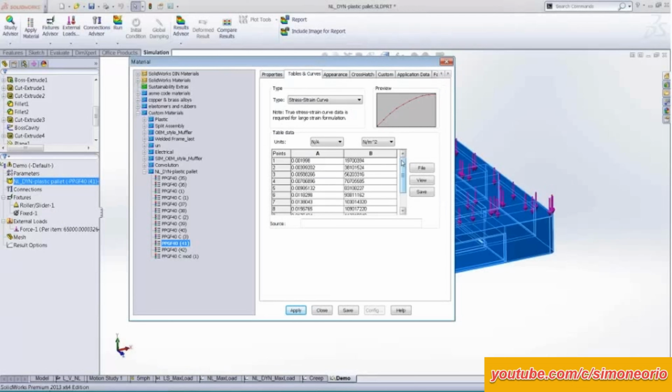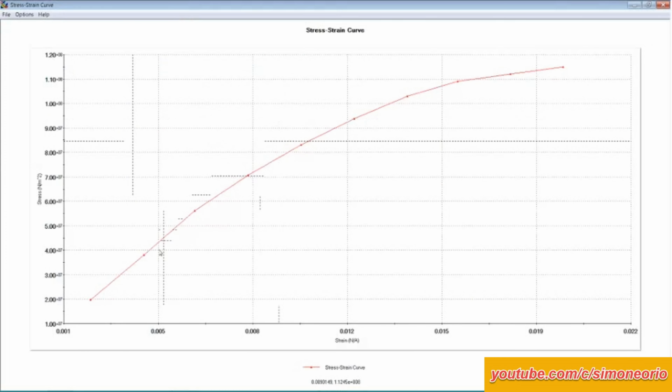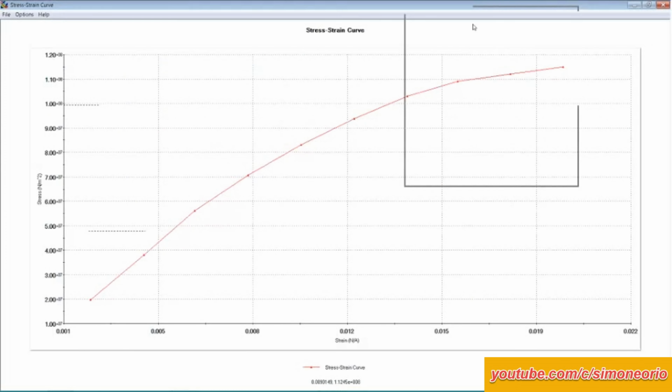Otherwise, you can go to our blog, and there's a couple postings on other locations, commercial websites, a lot of them that are free. And I have one that I go to a fair amount to get this data from. And we can just cut and paste it into the model, just like Excel. And this is our stress strain curve for the glass-filled polypropylene.